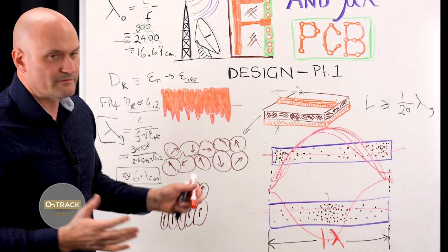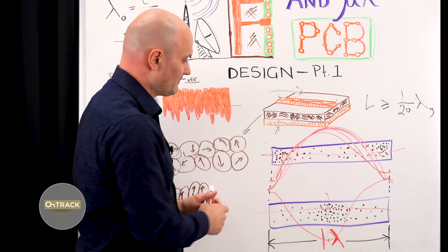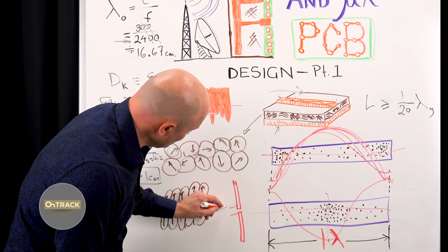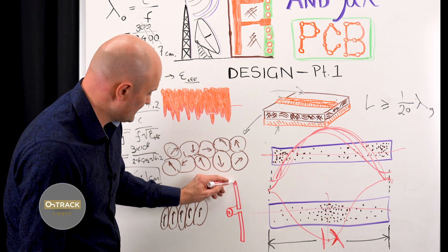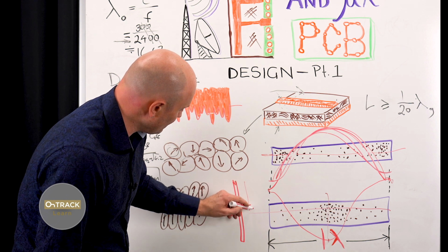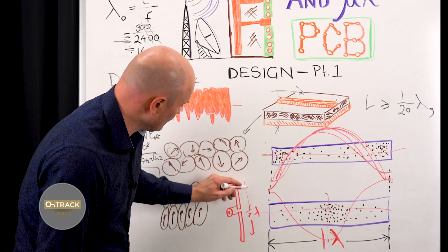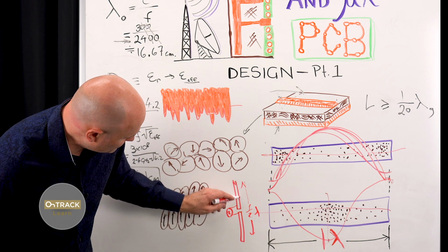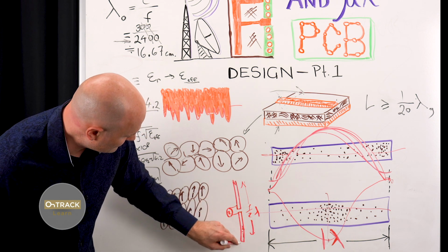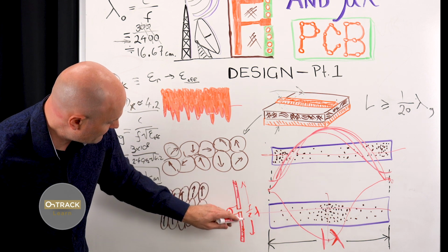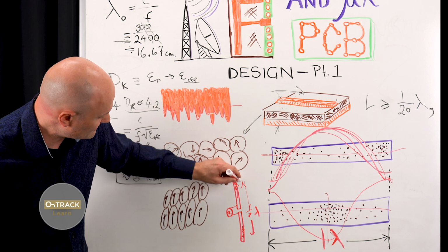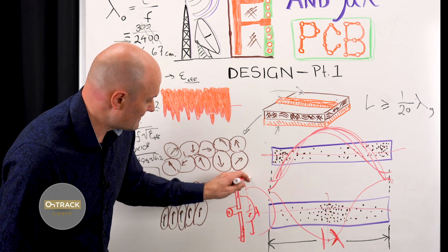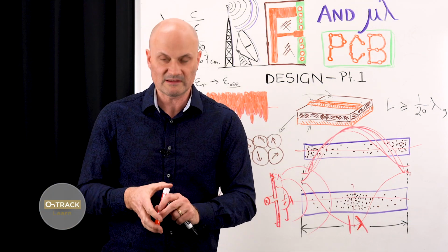Most people have heard of the term dipole. A dipole is effectively a piece of metal, or two pieces of metal like this, connected to an oscillating voltage source, and this whole thing is one half wavelength apart. At one instant, this voltage source pushes all the charge down to one end, and it's very negative here and very positive here, and then it reverses and pushes all the charge back up, so it's very negative here and then very positive here, and that gives rise to propagation away from that. And this is how antennas are built. This is how antennas work.